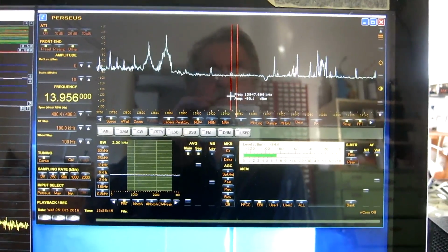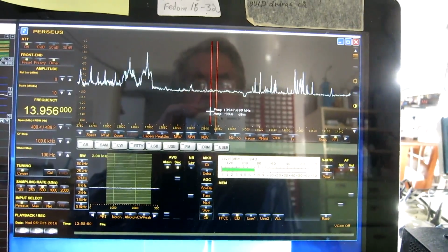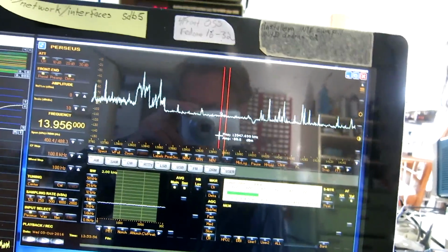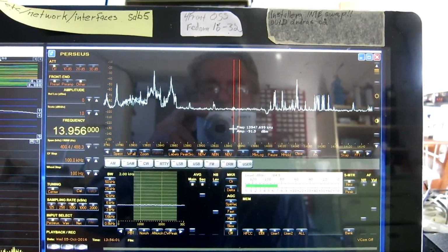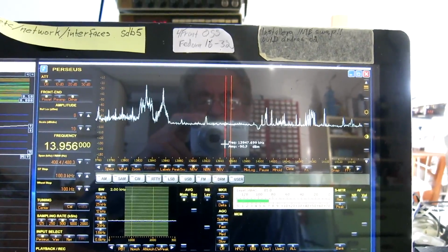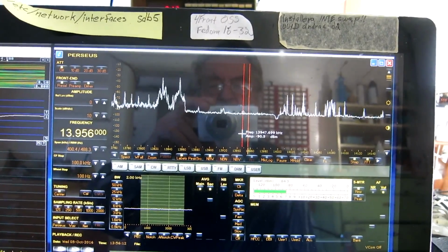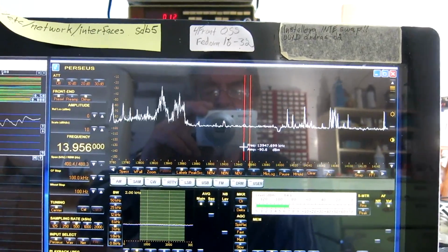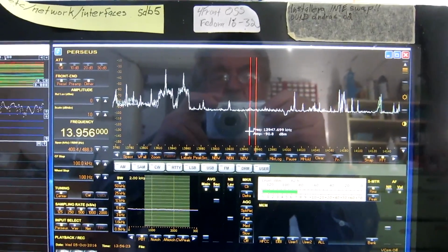Without the pre-selector, the noise floor is at minus 85, and it's the same in the notch, minus 117. So the difference in the noise floor from the antenna and from the receiver itself is 32 dB. 10 dB is what is enough for no losses of performance. So there is a margin of 20 dB without the pre-selector. And that's the same for both receivers.